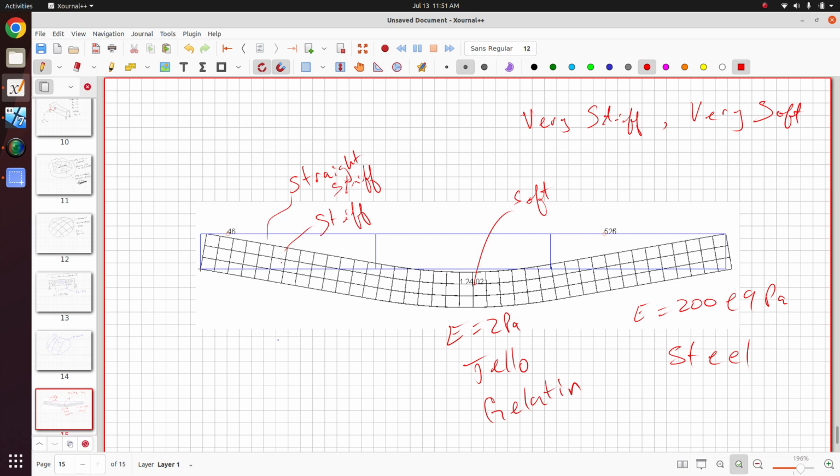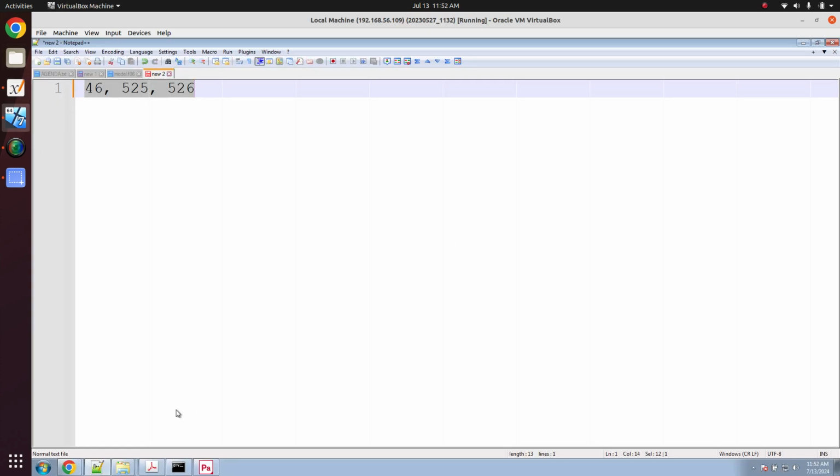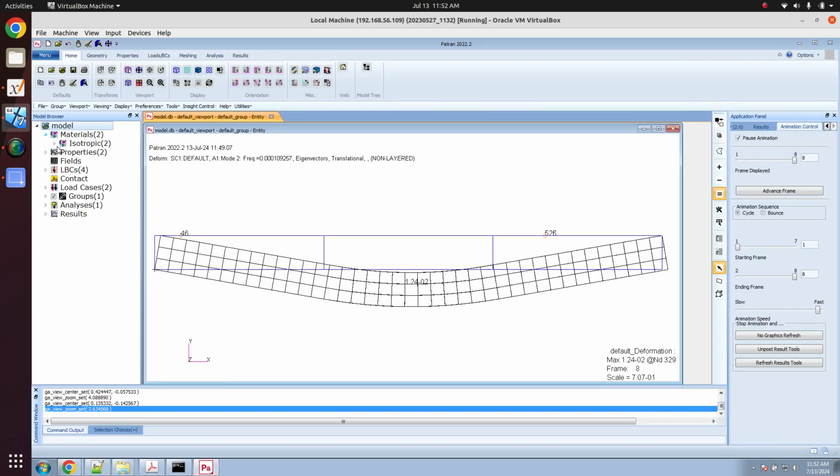This is a problem because part of the structure is going to remain almost in an undeformed state. So here, it's still perfectly rectangular. It's not deforming for the most part. The same for this. It's almost a mechanism, but here we get some deformation. So this was flagged to us. This is why we got the user fatal message, because of the very high and very low stiffnesses that were being used in this structure. Now, what do you do in this case if you want to fix it?